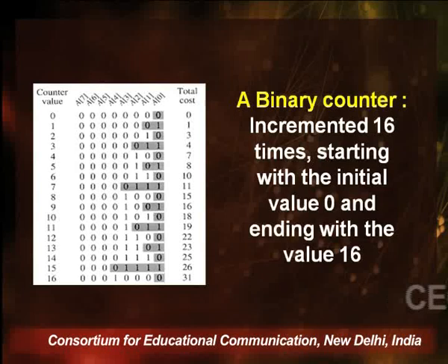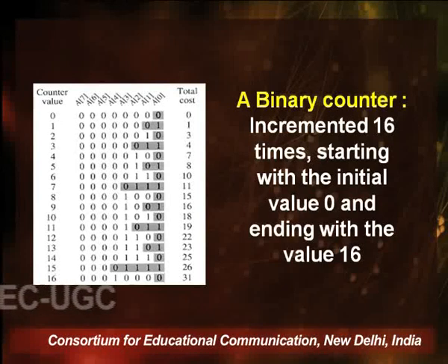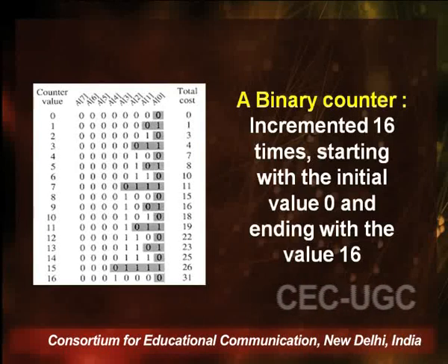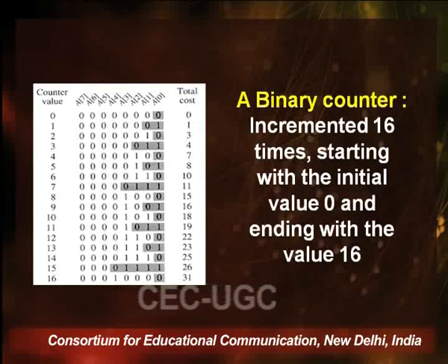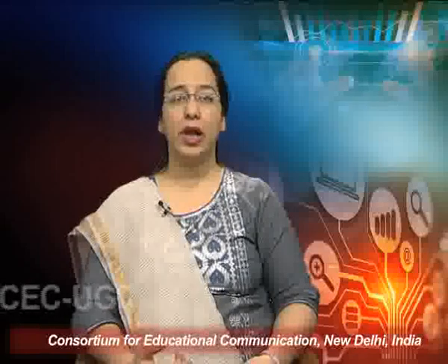So every time, can we say that all the k bits are flipping? No, it is not happening, except in one instance where all are 1, and at the time of reset of the counter all the bits become 0. That is the only operation in which k bits are being flipped, while in other operations we cannot say that all the k bits are being flipped.